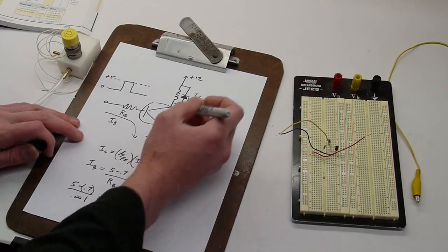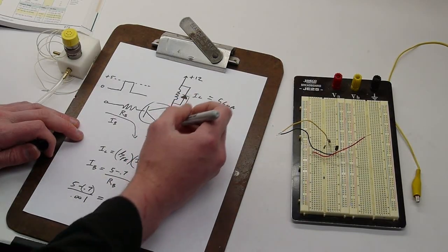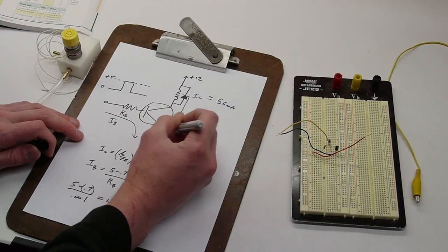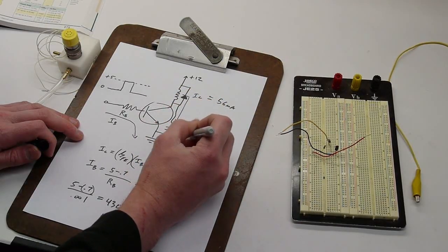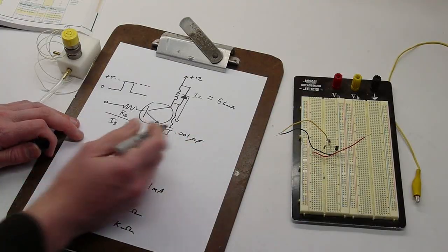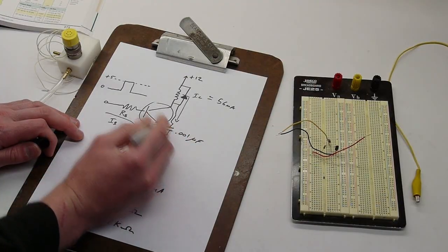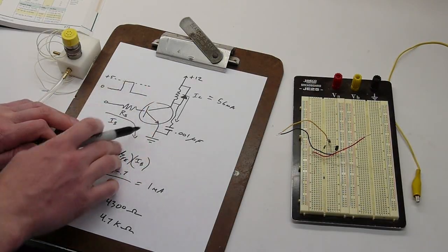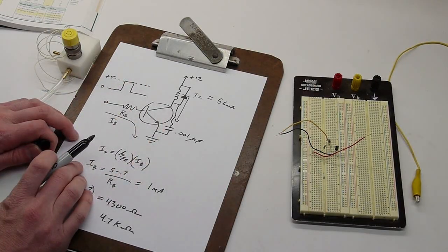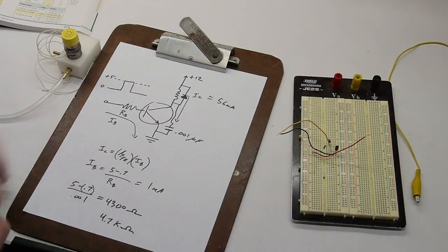And you can also take it one step further and add a capacitor in there as well, like this. And this can be small, like 0.001 microfarads. And the capacitor will smooth out the pulse here and give the diode time to turn on and make sure that there's absolutely no spiking or voltage rising going on in here. So let's build it and test it and prove that the thing actually works.